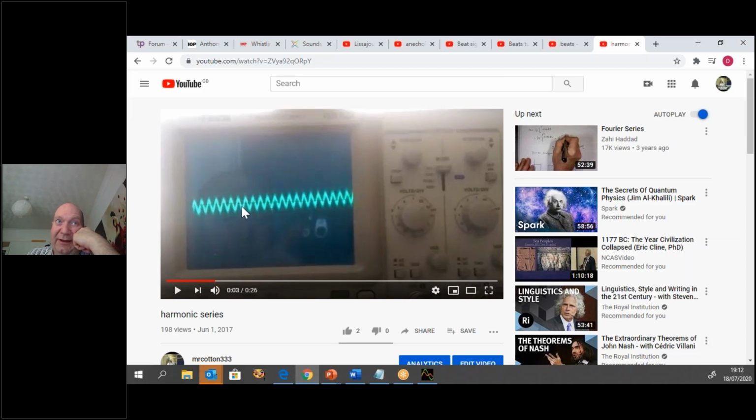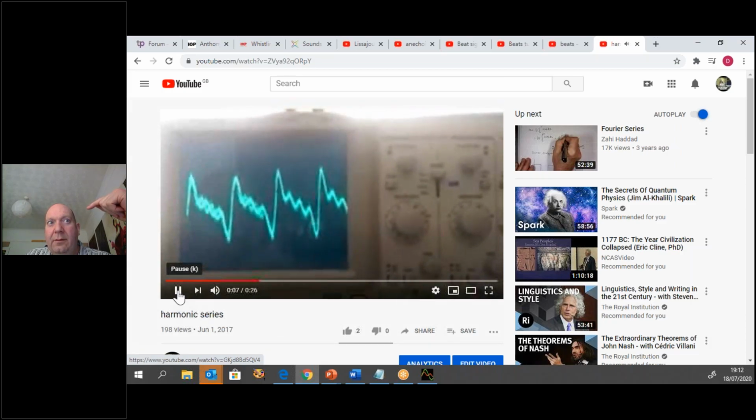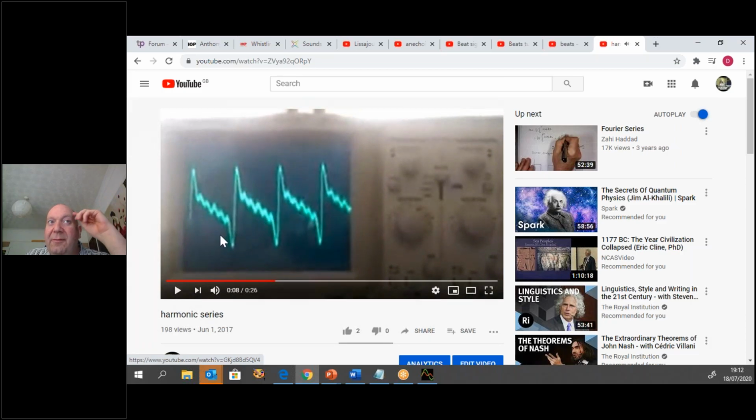Each one you can see, and then now we start adding them in. And what's amazing is you start to see it build up. And this is what Fourier is, you're building up those individual frequencies. As you add all those multiples of the fundamental frequency, each term makes it more and more like a saw wave. And then the last wave is a real saw wave.